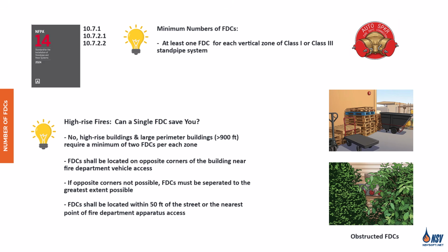In addition, fire department connections must be clearly visible and recognizable from the street or the nearest point of apparatus access. And finally, FDCs must be located within 50 feet of the street or the closest fire department access point.